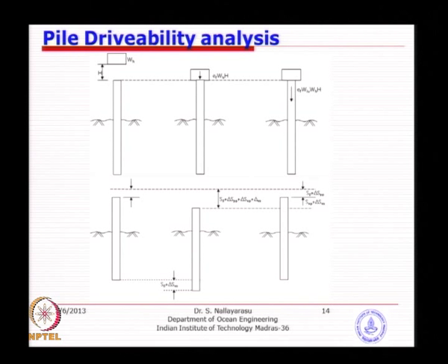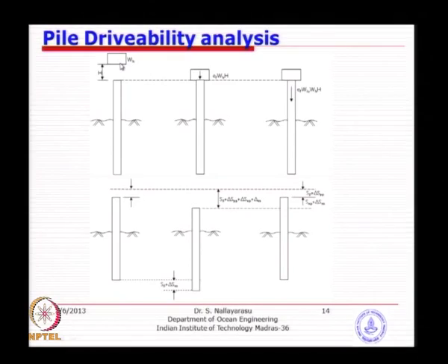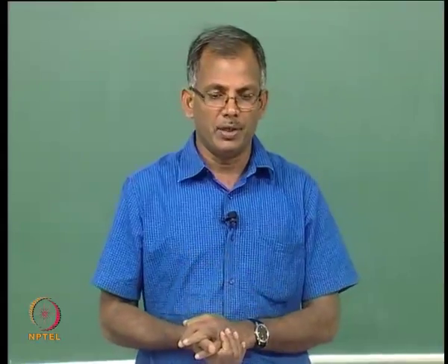So, what you can see in this picture is the pile is into the ground at a certain level, just halfway through we are analyzing it, or you could actually have the pile just resting on top of the seabed and trying to drive, dropping from a height of h with a weight of WH, which gives you the impact energy, basically the weight times the height, and the energy efficiency of the hammer itself, the internal system, how much it is, 90% or 80%, depending on what.